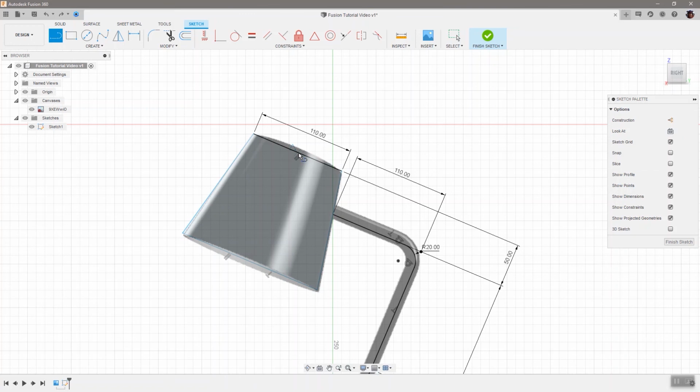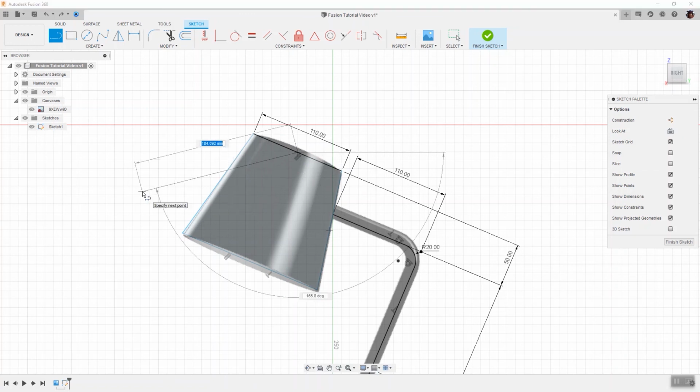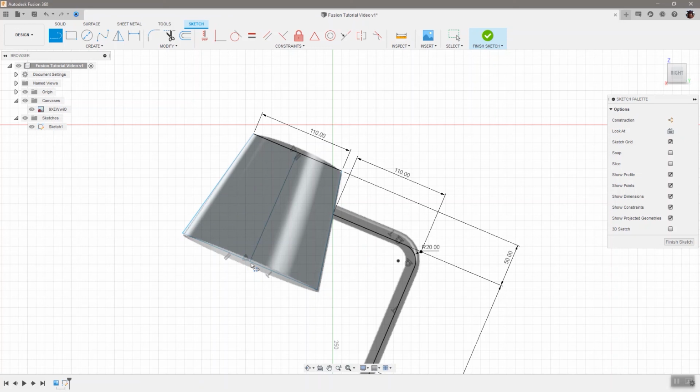So now I can click on it, and I'm drawing my first line. If I do the same thing along the bottom line, patiently move along, you'll see that blue triangle turn up. That is the midpoint of the line. And if I just click again, I have a midpoint. And it's quite nice, because that midpoint will allow me to create a symmetry condition.